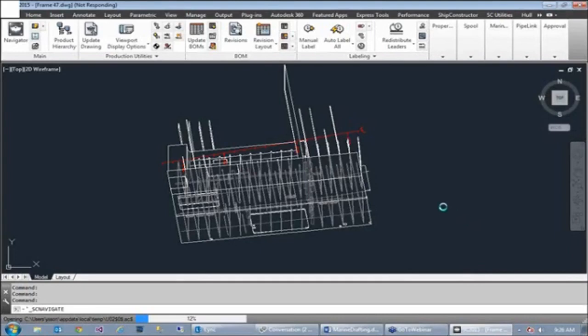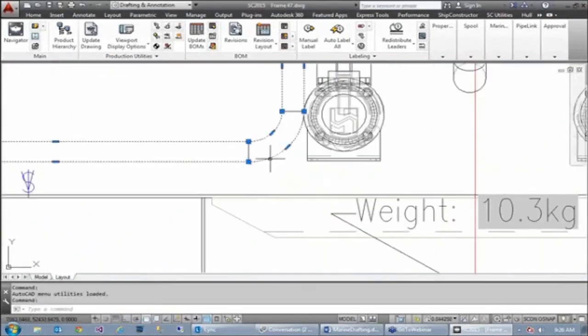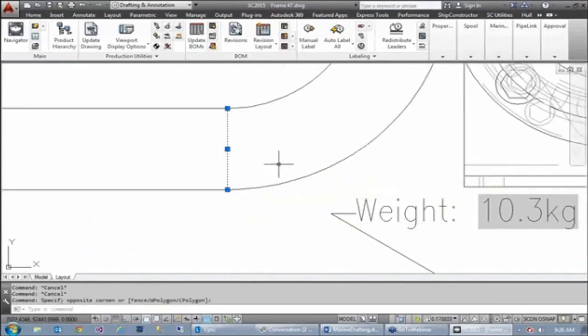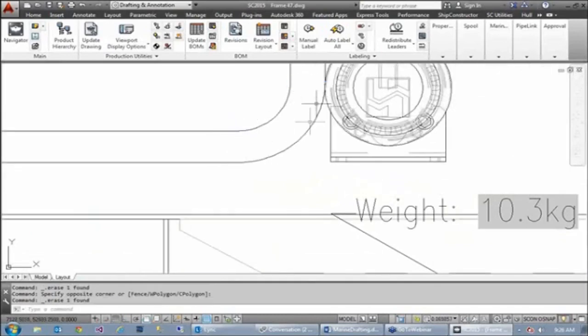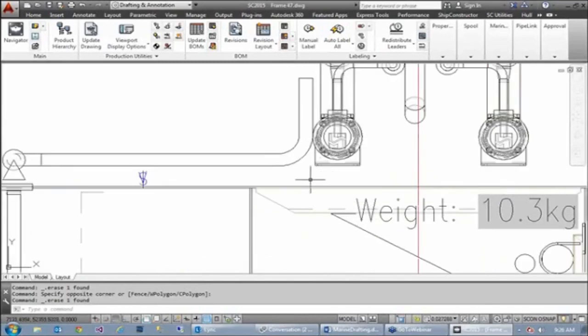Well, essentially it's doing a hidden line removal of that object. So you see those bends right there? Okay, I see what you're saying. Right there would not be shown in the piping drawing. Right. And if you delete those and you update, do they come back? No, they won't come back. So if I update this drawing now, it won't come back. So that's my question. It requires manual editing, but still you'll be able to get rid of them. They're just dumb lines. Correct. There's no way to process this to know what's fitting and what's pipe and to hide this stuff as you extract it or as you process this marine drawing.